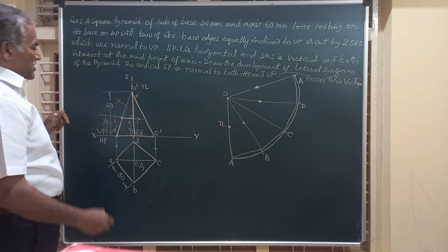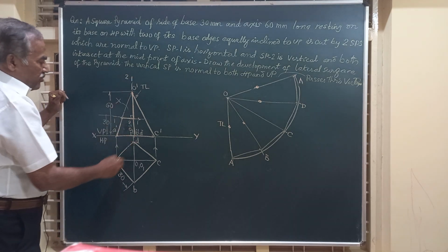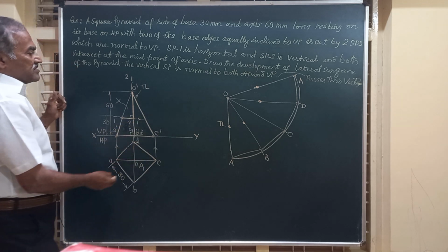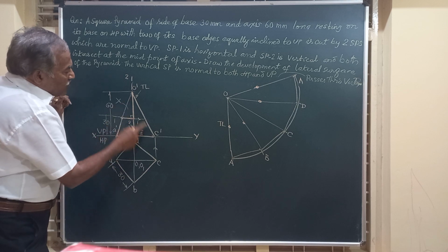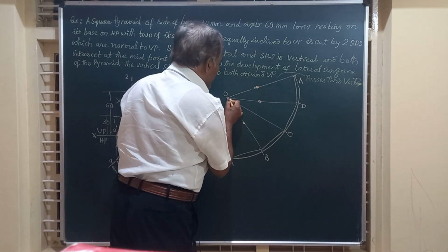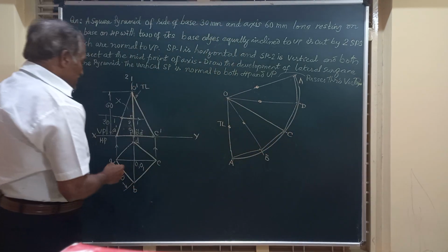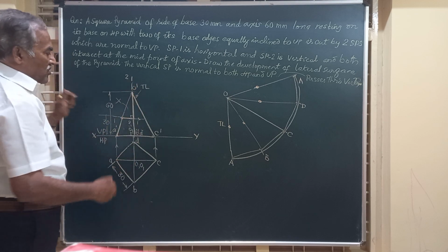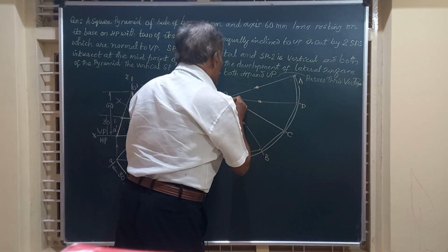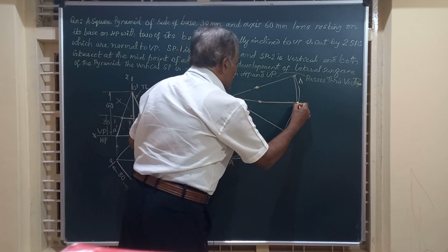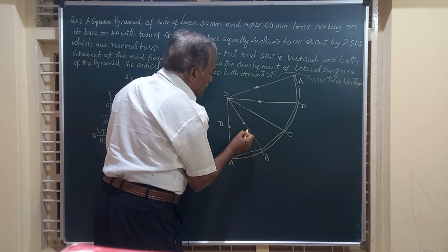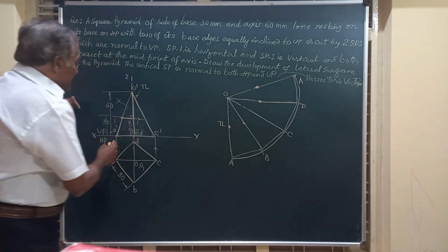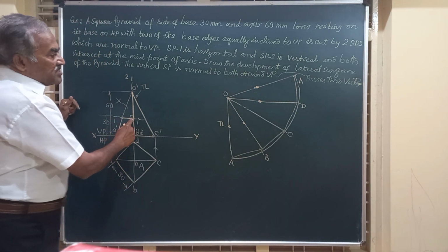And finally friends, the section plane is passing through this point, that is it's meeting here. And if you observe this friends, the line OC is intact, so that is available. This OC, we have OB and OD, all these are retained. So I am going to show them by full line. OD full line, OB full line, and only on these edges, OA or OB and OD, this part is removed.